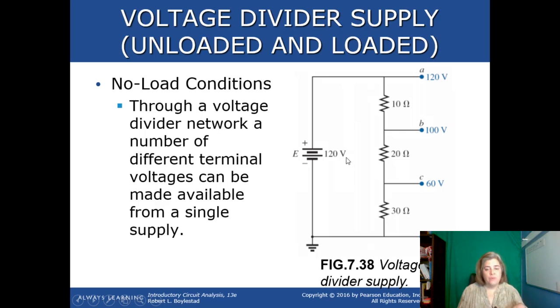So if you want to prove this to yourself, you can pause the video and work through it. Again, these are just meter measurements. This is not a circuit of any sort out here, so we're just measuring what voltages should be there under no load conditions. That means we don't have anything connected to A, B, C at this point.